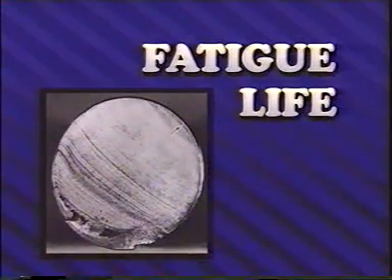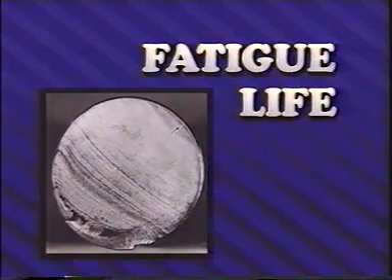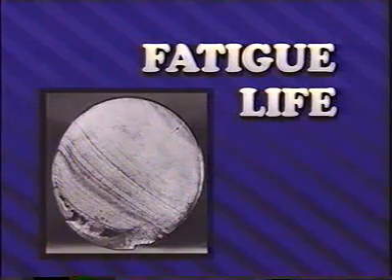Depending upon the metal involved, the environment, and the circumstances of stress, the final fracture may have ductile or brittle characteristics. Fatigue life. Predicting the fatigue life of a part or component is complicated. The part can be highly sensitive to small changes in loading conditions and local stresses. The local surface characteristics and the microstructural characteristics of the material also play an important part.